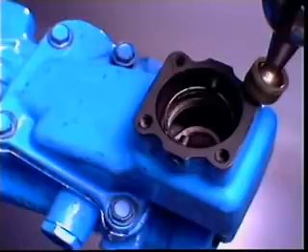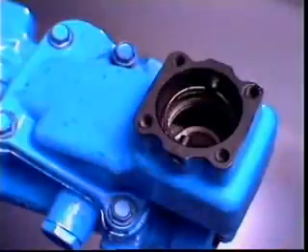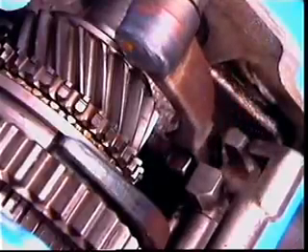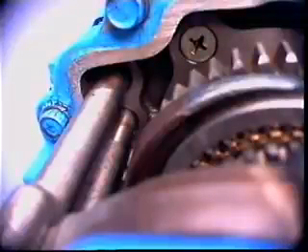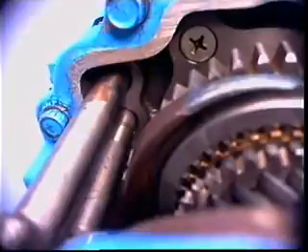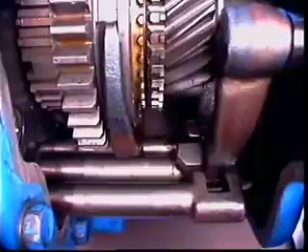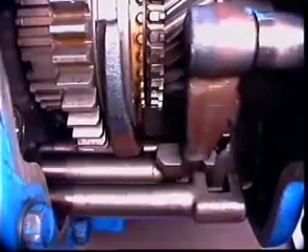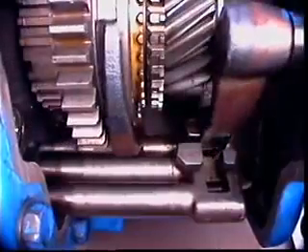In this design, the lower end of the gear lever fits into a socket in a control shaft inside the transmission extension housing. A short lever on the other end of the shaft is located in a selector gate, formed by slots in the 3 selector shift rails. They are supported in the casing and are moved backwards or forwards by the lever. One rail moves to engage first or second gear. Another serves to engage third or fourth, and the other operates fifth or reverse.